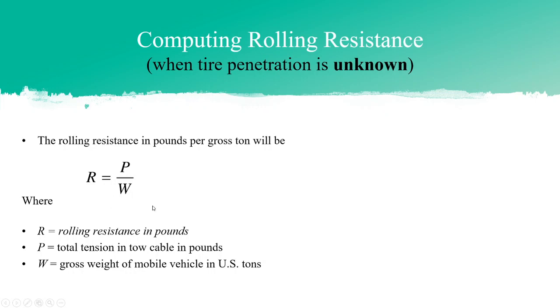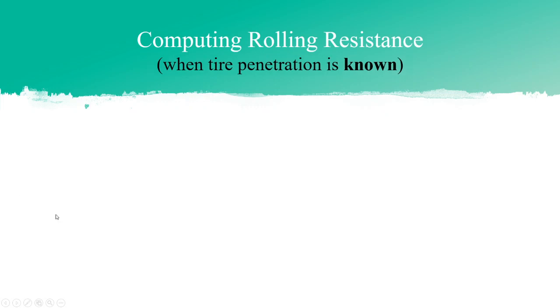But when I got a heavier machine, it could move on the same surfaces easily, okay. So there are other factors involved, but one reason was the weight of the car. So technically, for lower rolling resistance, you need heavier cars or machines.